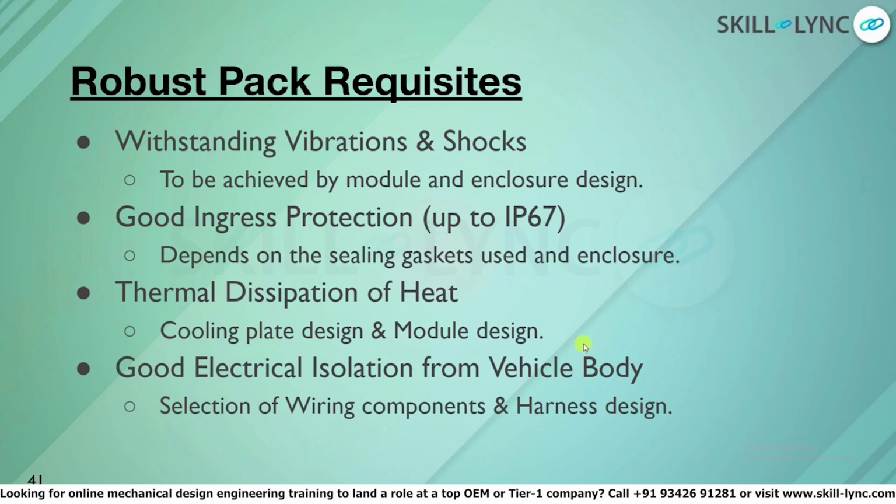One important consideration is that whenever screws are used for critical components like sensors, you could always use a thread sealant, so that with the right torque the screw is held well and doesn't loosen. And then the next most important part is good ingress protection. This is very important: all the enclosures must be properly sealed. It has to prevent water and dust entry, as these battery packs are used in buses, which could be rooftop or chassis mounted. There is going to be a high probability of dust and water.